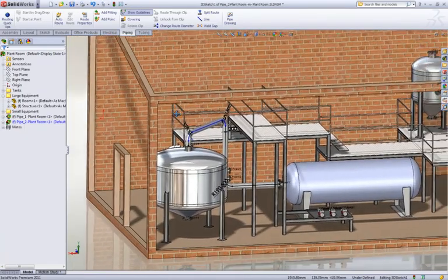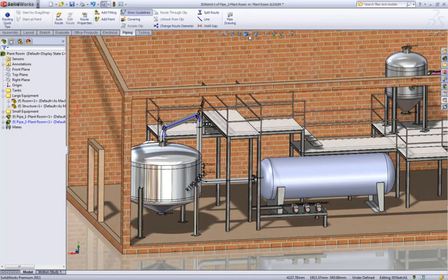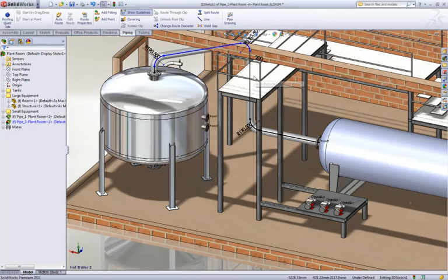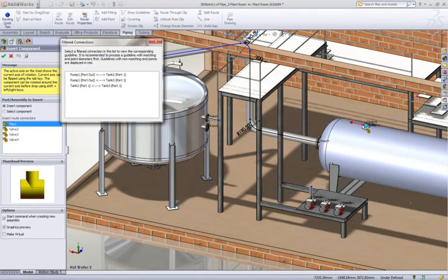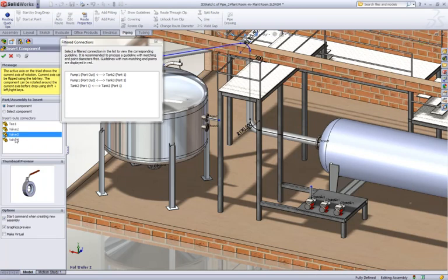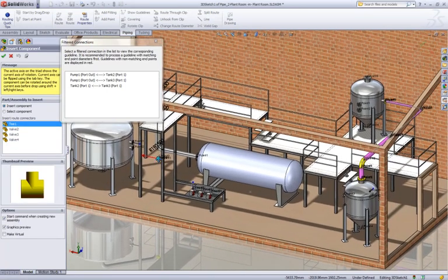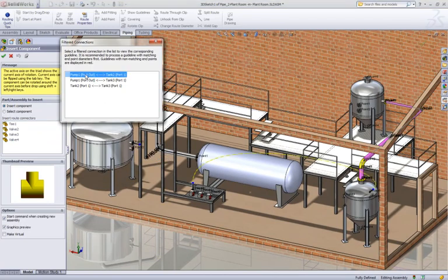Let's add the next route, which needs a number of extra fittings to be assembled. Of course, it's not possible to add these fittings until the pipeline is placed, so a new dialog called Filtered Connections shows all the individual pipe sections without the fittings. This gives a clear understanding of where the pipes need to go.